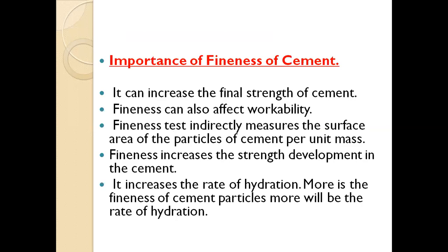Importance of fineness of the cement. It can increase the final strength of the cement. Fineness can also affect the workability. The fineness test indirectly measures the surface area of the particles of the cement per unit mass. Fineness increases the strength development in the cement. It increases the rate of hydration. The more the fineness of the cement particles, the more will be the rate of hydration.